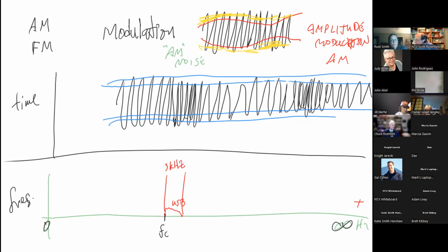What that means is now that other station, which was right there and interfering, is now out of my passband, and I'm out of his passband, and we are not interfering with each other, which means that we basically made better use of the band, which is great. That's exactly what we want. We want to make better use of the spectrum because it's a limited resource.